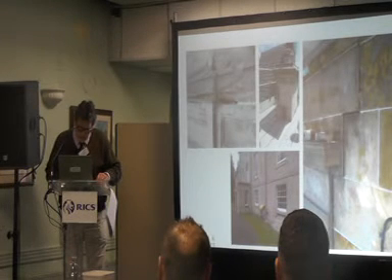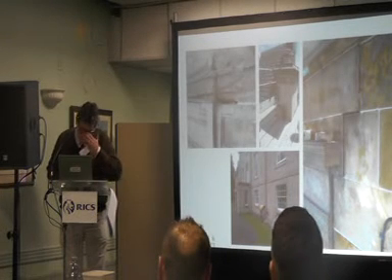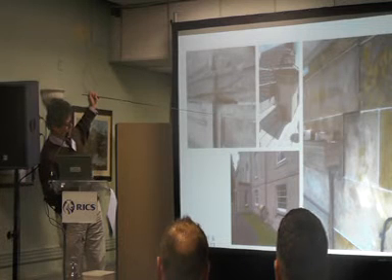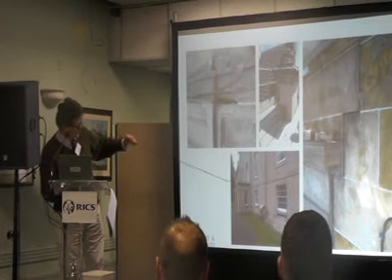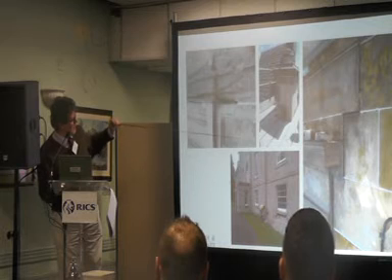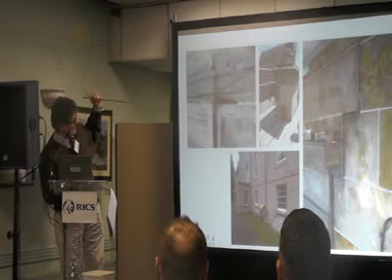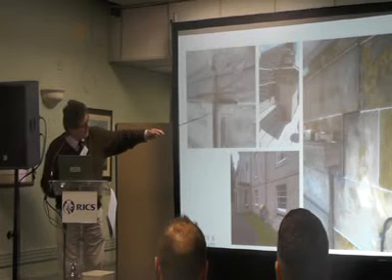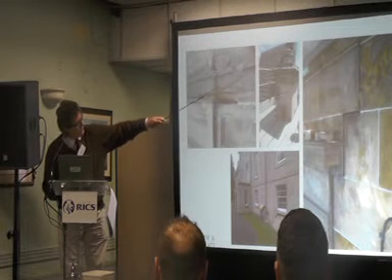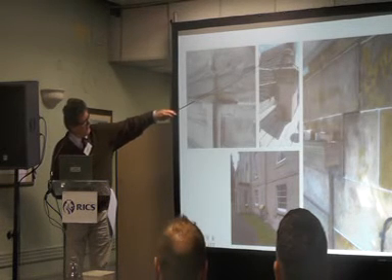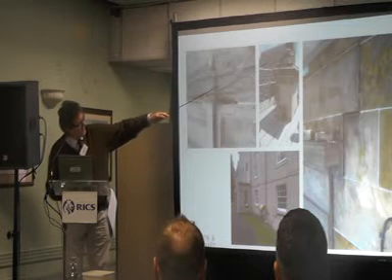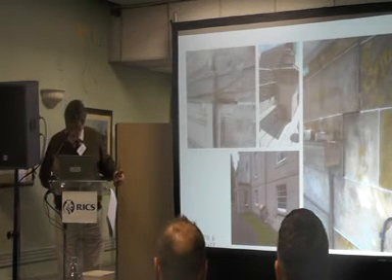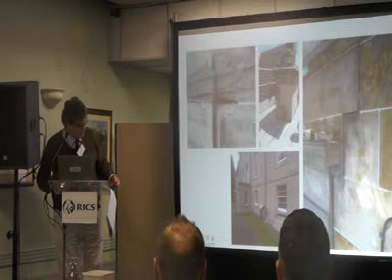And we've got some nice examples here. Plastic repair. Are these all Elgin High Street? No, that's not. That's again the house with the big roof, big new lead roof. Plastic repair, it's all right. It'd be better if you could afford to make new stones, as we did here on this chimney. And just while we're on the chimney, those elephant's foot vented caps, that is, in my experience, the best way to cap off an unused flue. Birds can't get in, but the air can circulate.